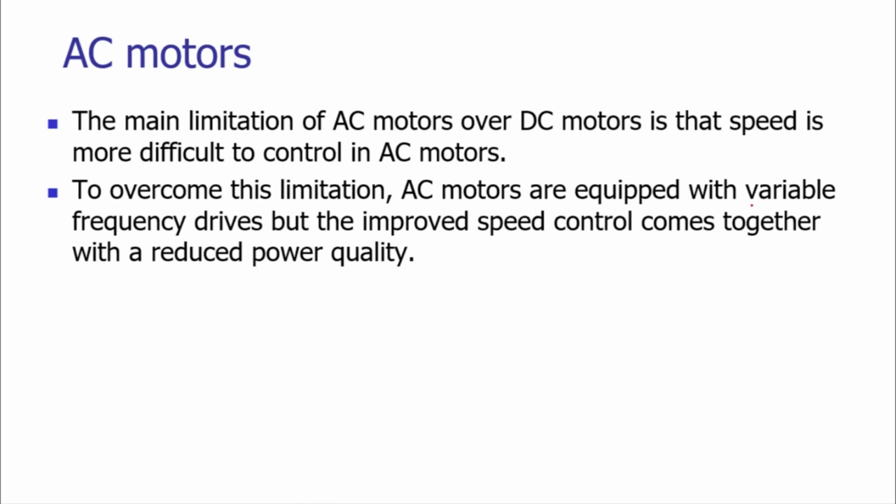Variable frequency drives means we have to have an arrangement which will provide variation in the frequency that is to be applied to the AC motor. In general, AC motors work with a constant frequency. But for our intended application, we may require variation in the speeds, the variation in the velocity of the spindle. So for that purpose, we need an arrangement which will provide the variable frequency of the AC current that is to be applied.